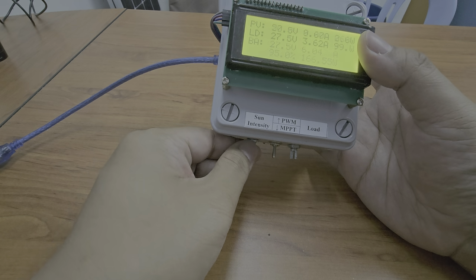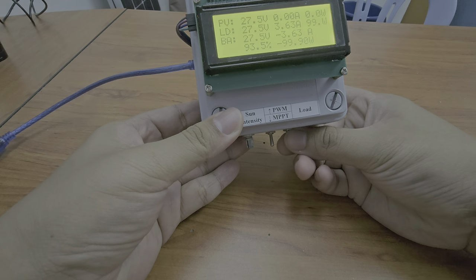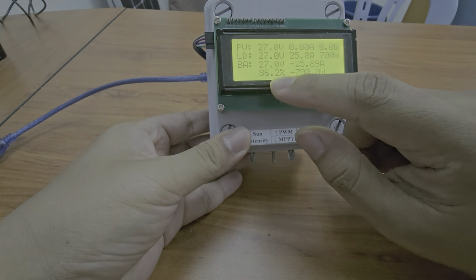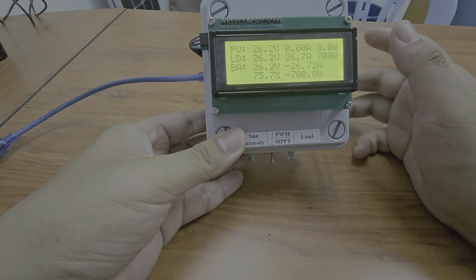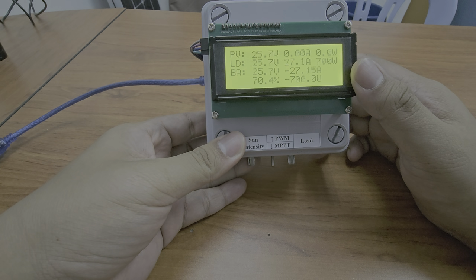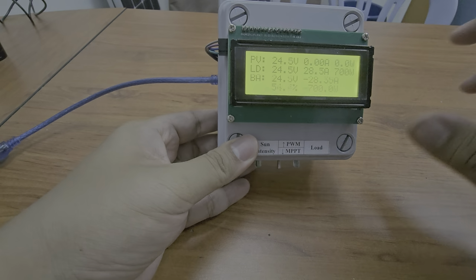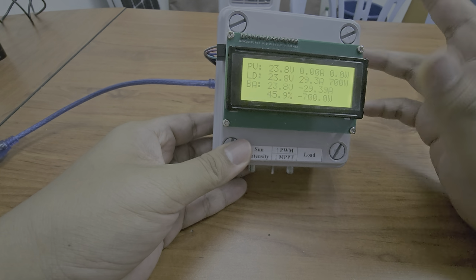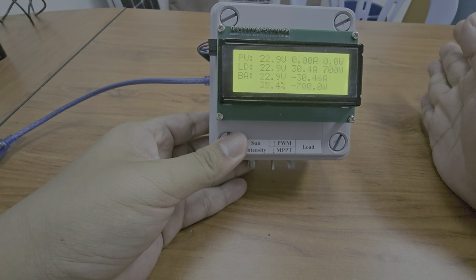What happens if the battery is depleted? Here I increased the load a lot, to 7,000 watt. You can see the battery drops significantly, and the voltage also drops significantly. It's okay because I set the battery quite low. You can see the discharge will stop, if not mistaken, at 20%. Same as before, if you don't want your battery to be damaged, you cannot just discharge everything from the battery.